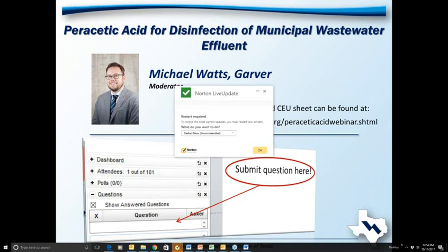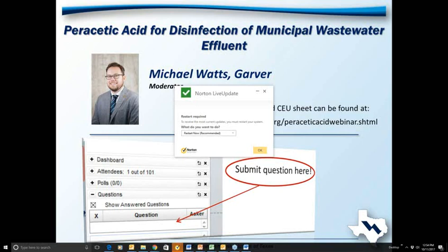Since there's no more questions, we'd like to add something. Something Sarah and I noticed is that if you look through the data, and from the data we've seen presented from other sites, it looks quite a bit different from the data on our site. So if anybody's contemplating doing this, we really urge you to do site-specific testing on your site, and then make a determination what type of disinfection system is going to be right for you. Excellent point, Leonard. I think that should also be a key outcome from this, is to do some kind of initial screening of your water with peracetic acid, and that could be as simple as some initial laboratory bench tests.